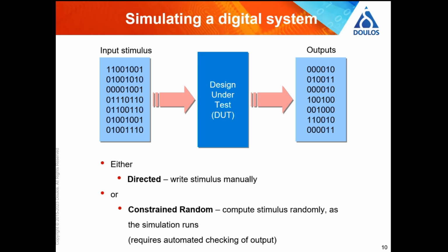You'd either write some random tests. Let's just try some random things. But there are certain things you need to test that it's much easier to just write the test yourself. Or you might want to put your design in a certain mode. There's no point in testing mode 3 if you haven't got some directed stimulus at the beginning of your test that puts the chip into mode 3. If you assign the mode randomly, whatever that means, you're wasting your time.